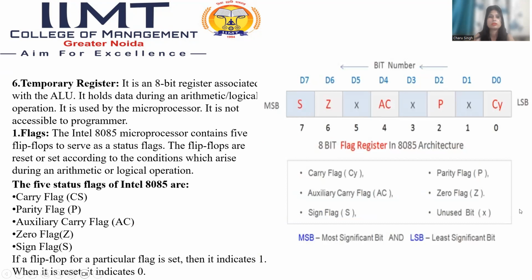Next, we have the temporary register. It is an 8-bit register associated with the ALU, and it holds the data during the arithmetic and logical operations. It is used by the microprocessor. It is not accessible to the programmer.